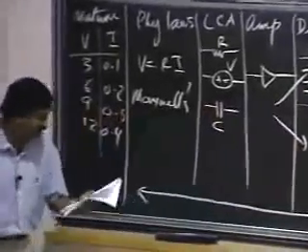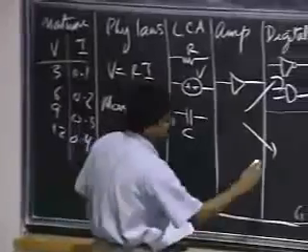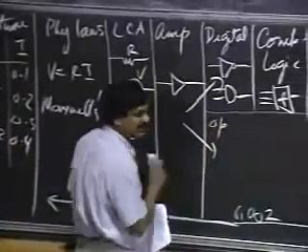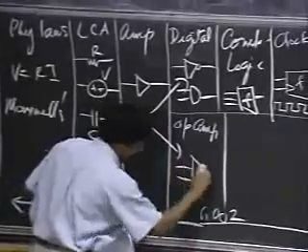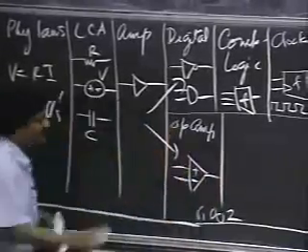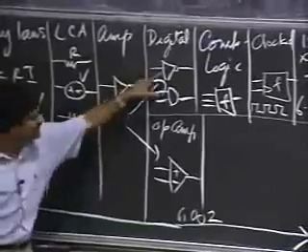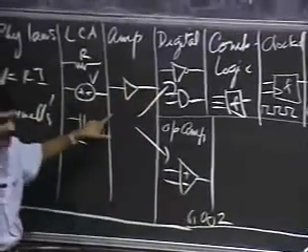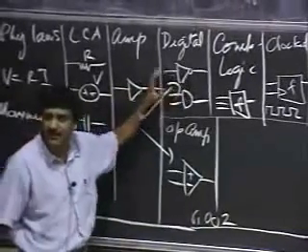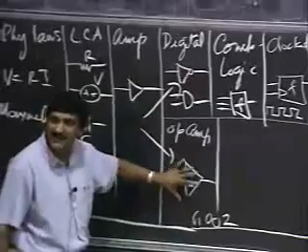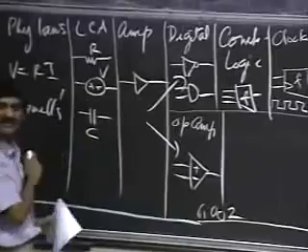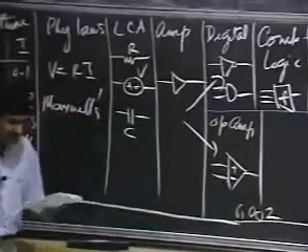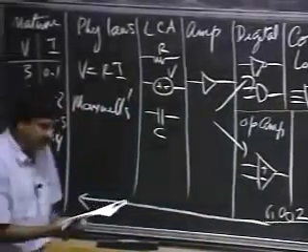So that's the one path. There's the analog path. The analog path takes an amplifier and builds an abstraction layer called the op-amp. See how similar they all look? The amplifier, the inverter in the digital world, and the operational amplifier in the analog world. Just slightly different ways of looking at the same devices. So to build analog systems, we build an operational amplifier.